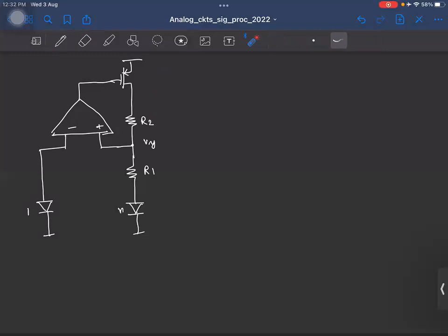So basically, I'll have one more CMOS. Right, so I'll do this. Right, so now for both the PMOSs, the gate voltage is same, source voltage is same, the current will also be the same. Okay. So now Vy is now VEB1.